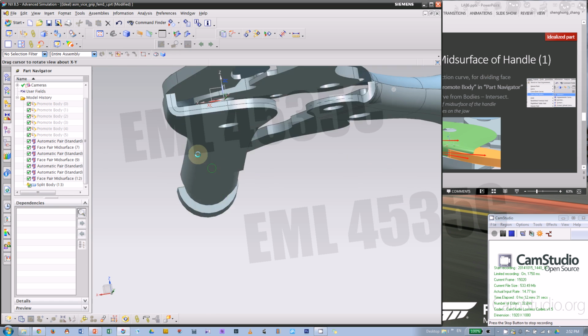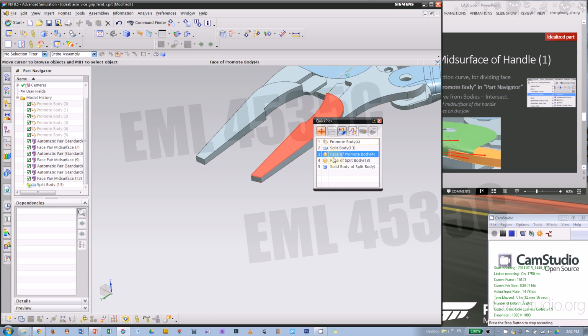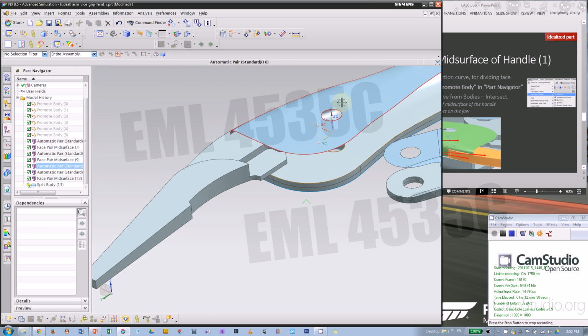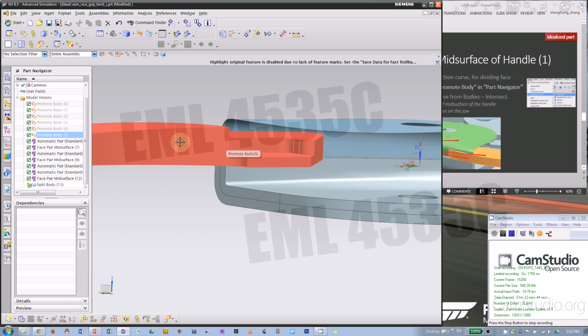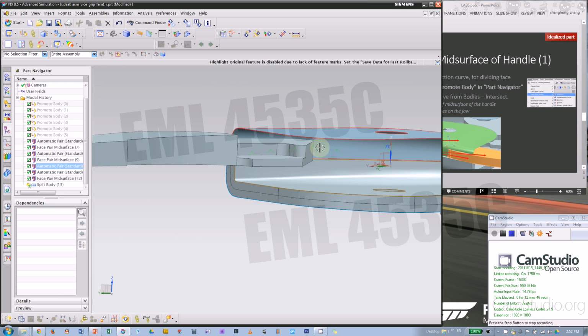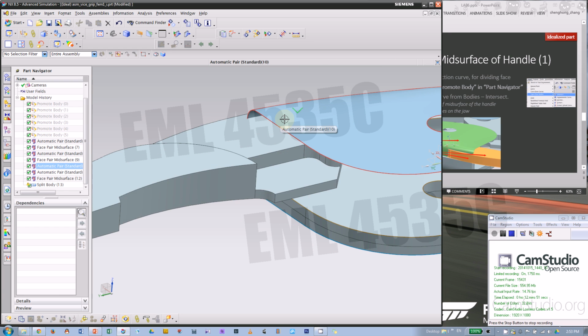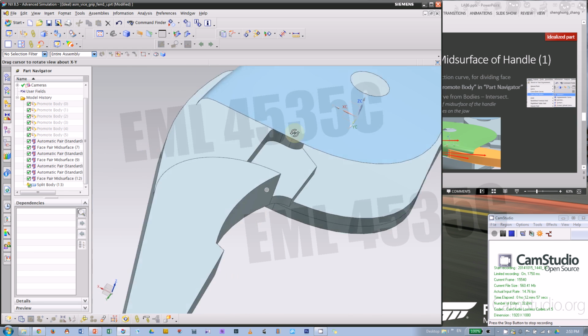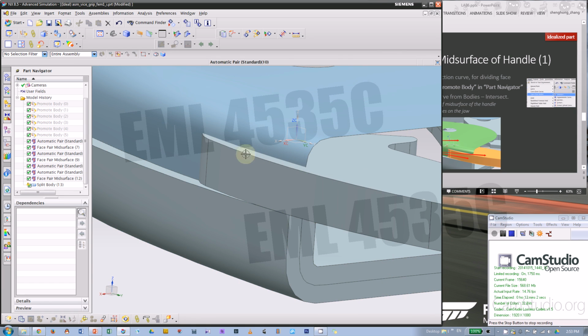Alright, anyway, so if you look at our CAD, the jaw handle portion, okay, it's actually not touching the midface. The jaw is actually not touching this handle piece, and in the simulation we have to glue them together. And there's a glue called edge to surface glue. So the idea is we glue this edge onto this piece of 3D surface.